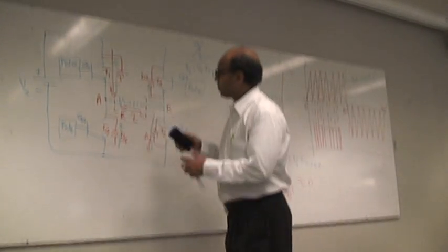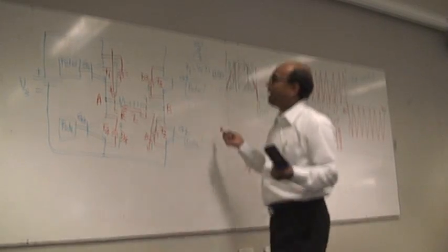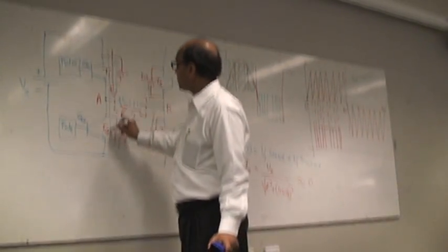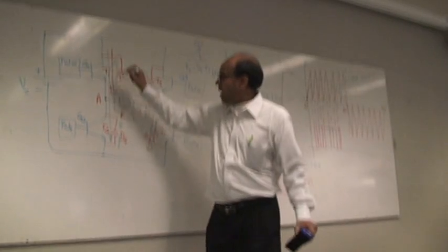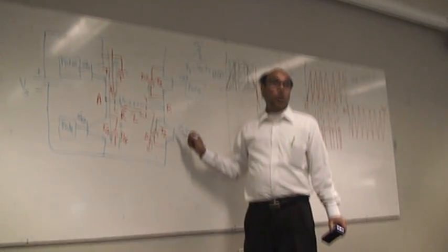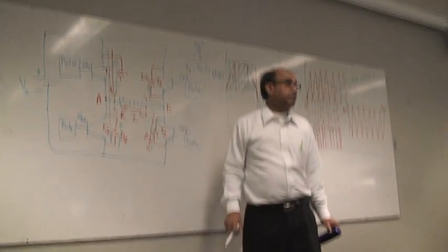Before I go to that, one more important thing is that while you design your control circuit for generating the pulse, the most important thing is that never ever give the pulse to 2 transistors in one leg simultaneously. Okay? Everyone understand that part? You cannot make T1 and T4 or T3 and T2 on at the same time. If you do that, what is going to happen?